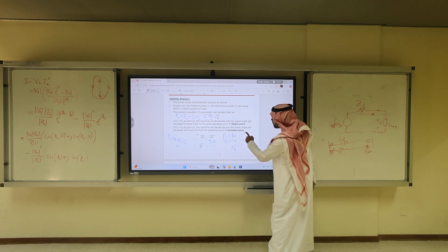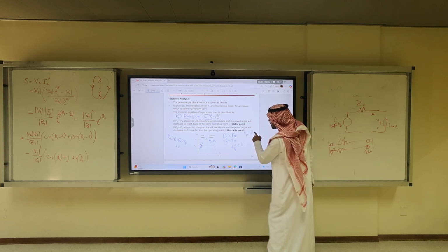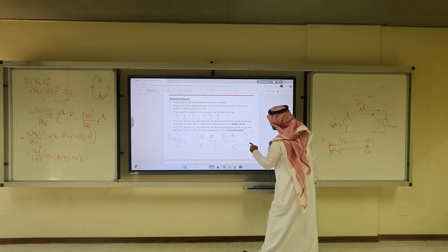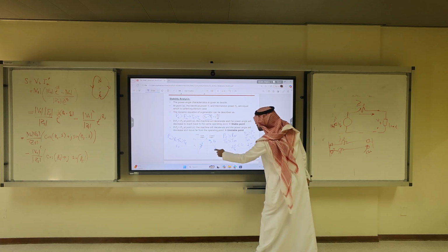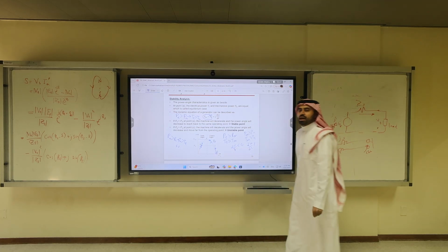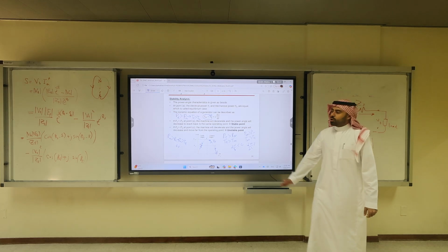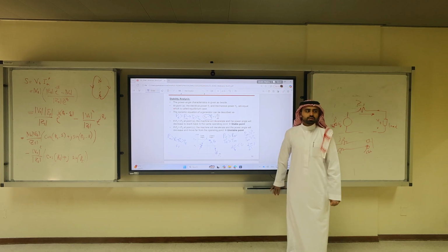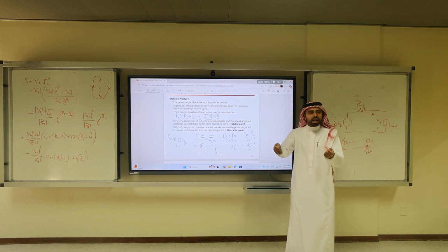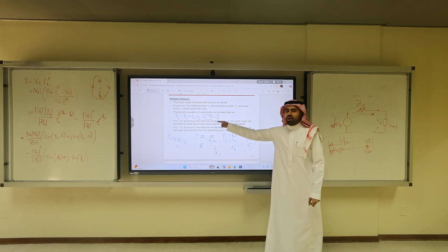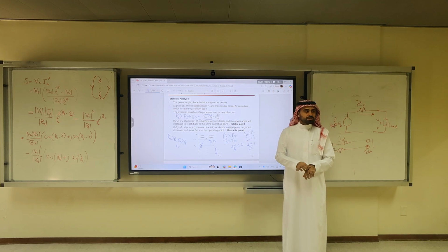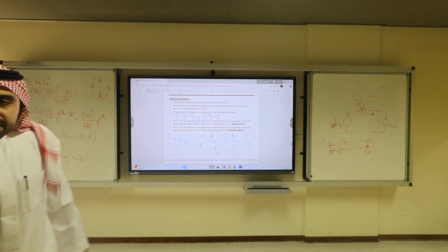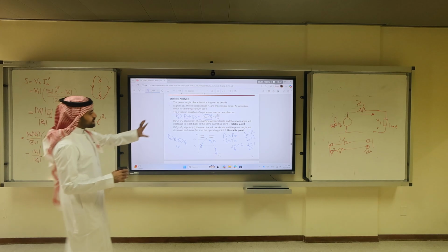If my mechanical input is larger than electrical, my mechanical torque is larger than electrical, my acceleration is positive, it means I'm drifting away here. That's why we call it the unstable region. The reason we call it stable or unstable is because the mechanical input power is governing my dynamics through the swing equation. Is it clear? I will share with you a file that explains the dynamics.